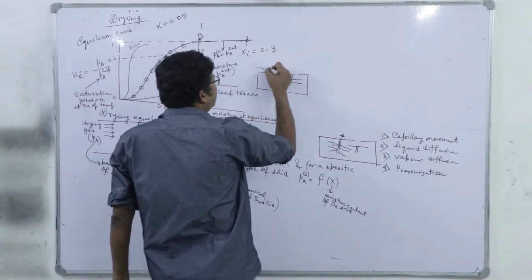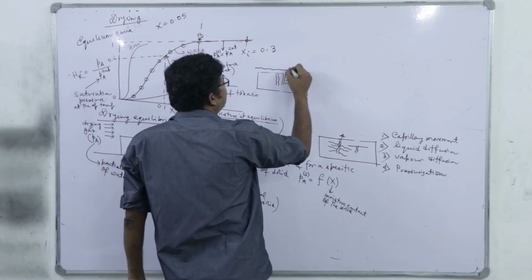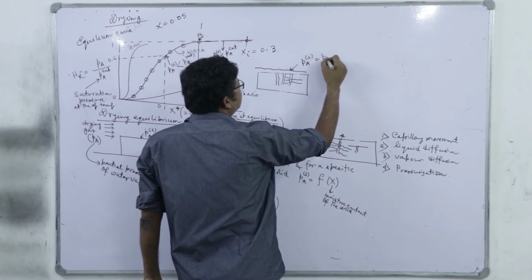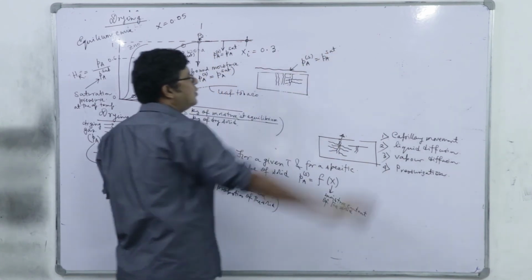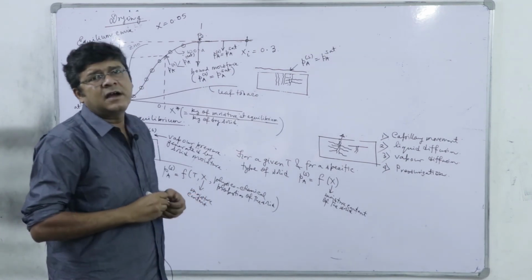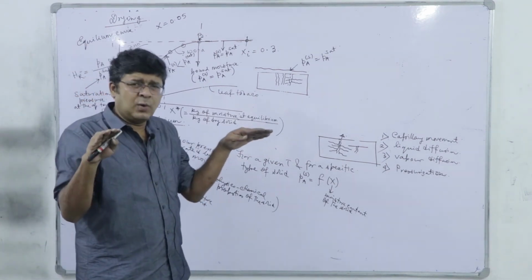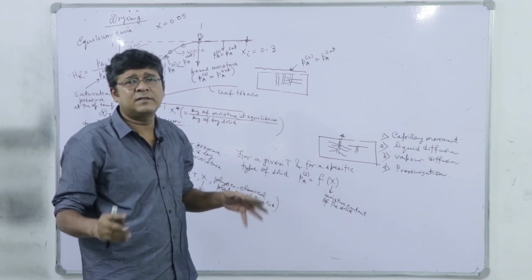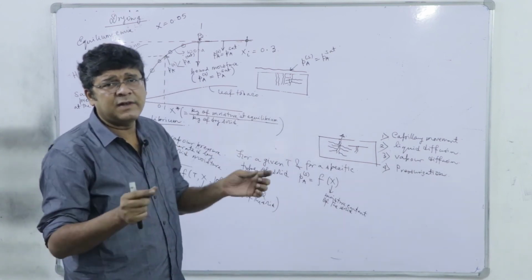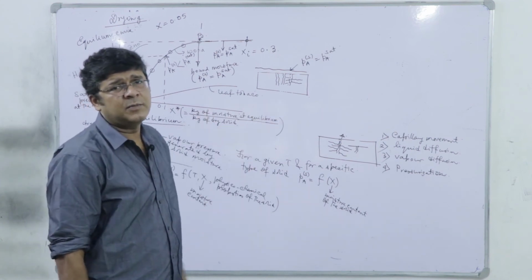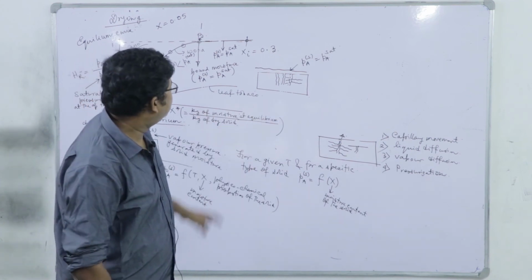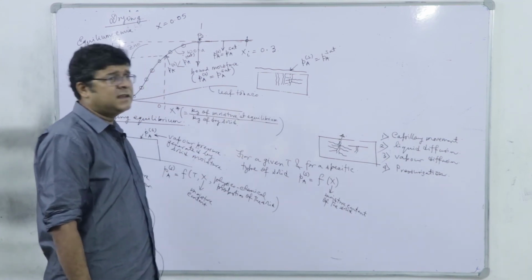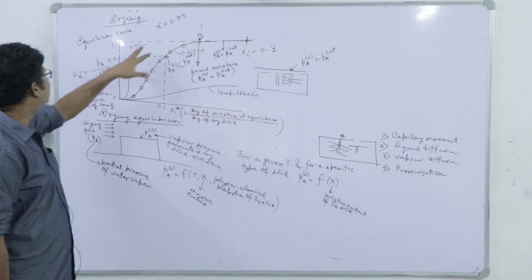See, if we have a film here at the surface, we will have PAS equal to PSAT, right, always equal to PSAT, because at the surface of water, however thin, whether it is an external film or a layer of liquid, it will always exert the vapor pressure of the pure liquid. So, that gives us an idea of bound moisture and unbound moisture, and additionally we have talked about this equilibrium curve.